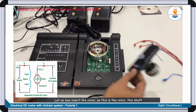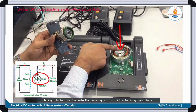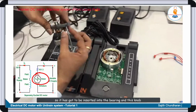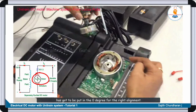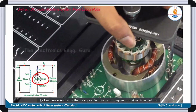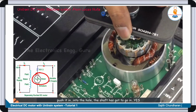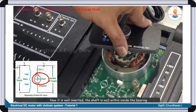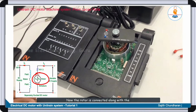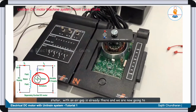Let us now insert the rotor. So this is the rotor. This shaft has got to be inserted into the bearing. So that is the bearing over there. So it has got to be inserted into the bearing, and this knob has got to be put in the 0 degree for the right alignment. Let us now insert, and we have got to push it into the hole. The shaft has got to go in. Yes. Now it is well inserted. The shaft is well inside the bearing. Right. Now the rotor is connected along with the stator, with an air gap already there.